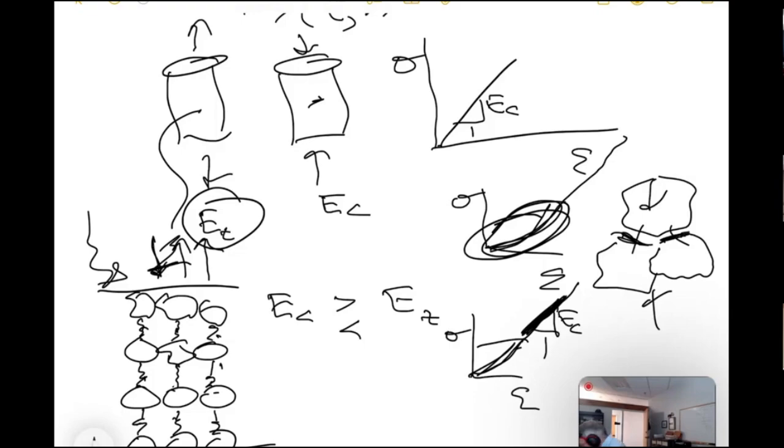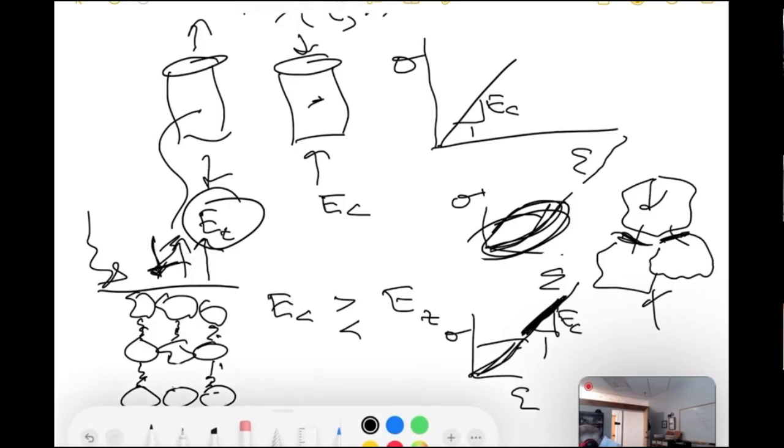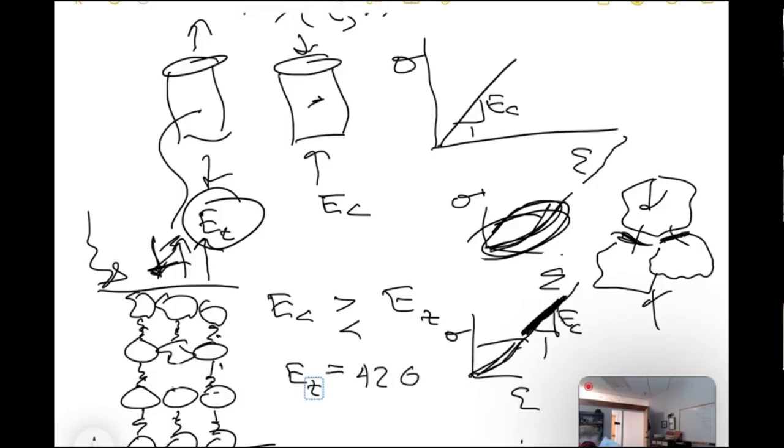And so that is going to be bigger than the tensile modulus because that formed later. The tensile guy didn't have a bunch of contacts in there. So when you pull it, there are no new surfaces forming. So it has a certain stiffness. But when you squeeze it, after it closes up, it has a higher stiffness. So the result is that for a typical Lac du Bonnet granite, the tensile modulus is 42 GPa, and the compressive modulus is about 69 GPa.